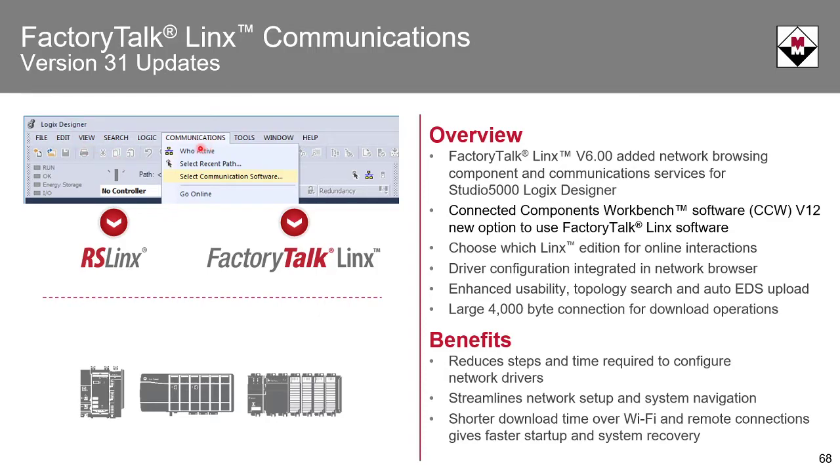So if you go to communications, there's this new select communication software where you have the ability to toggle between RSLogix or FactoryTalk Linx. Currently, Logix Designer still defaults to RSLogix Classic, but in version 33, when that comes out at the end of this year, I've been told that it will default to FactoryTalk Linx.